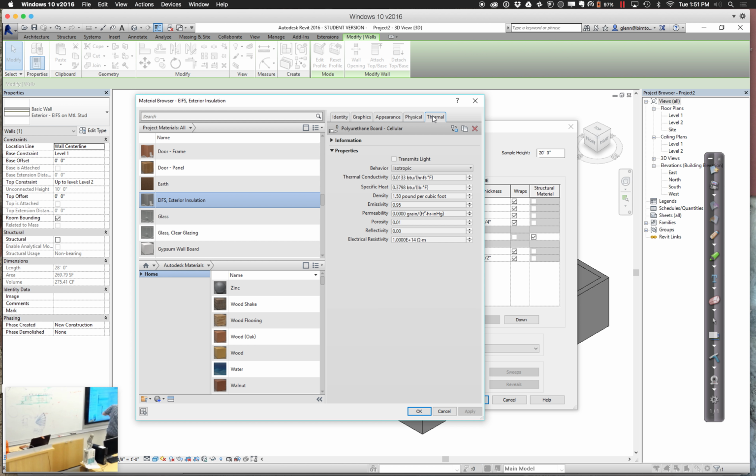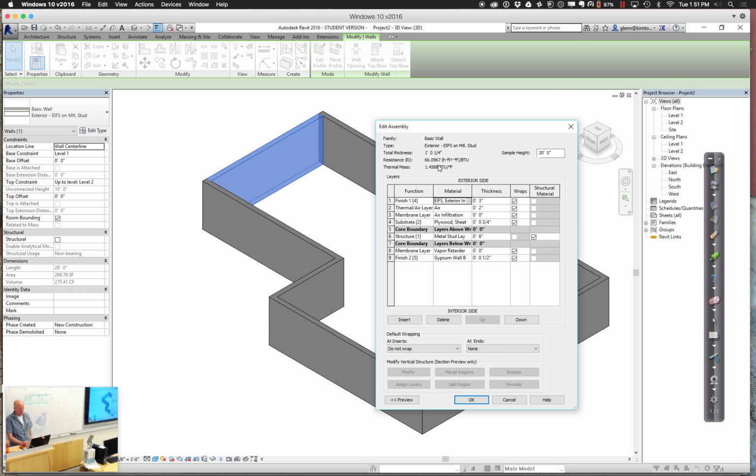But all those things add up to say that as we go through and increase things every inch, it's a linear behavior, and the R value will continue to increase in a linear way. Okay, so if I wanted to have a higher R value, what I would typically do is go through and add some more thickness, 3.5 or 4 inches or whatever it is.